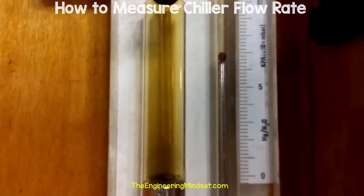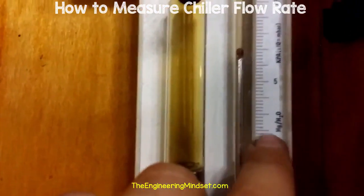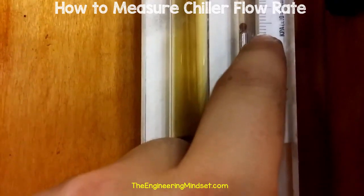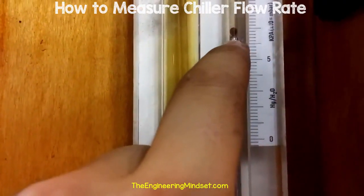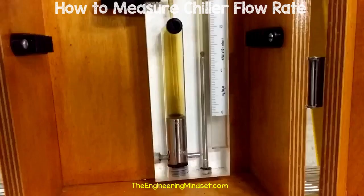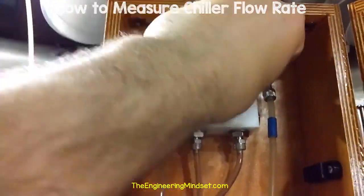Now just note that the little ball will likely move up and down slightly, and that's just due to the pumps and the turbulent flow within the pipework. Once you're happy that it has settled down, you can then take the reading. Here you can see it has a reading of around 6.2 kilopascals, and that's just the pressure difference between the high and the low side of the orifice plate. So just take a note of the reading and then you can begin to disconnect the equipment.